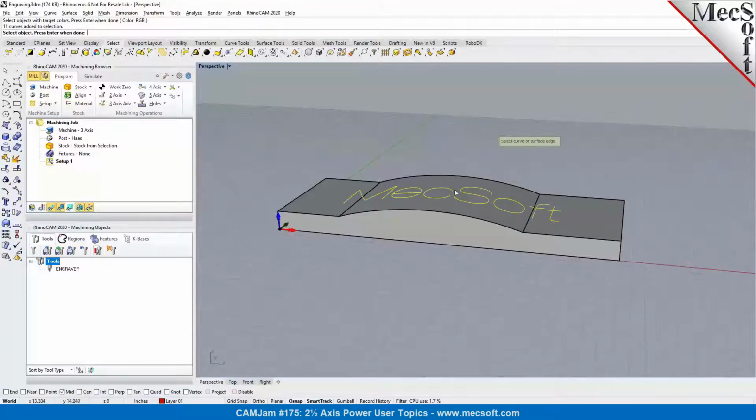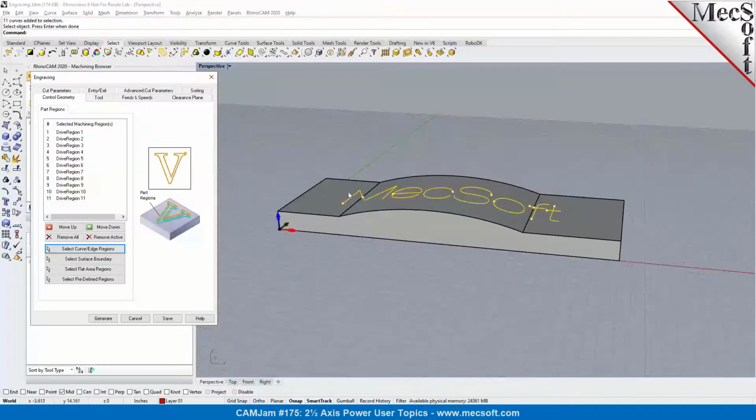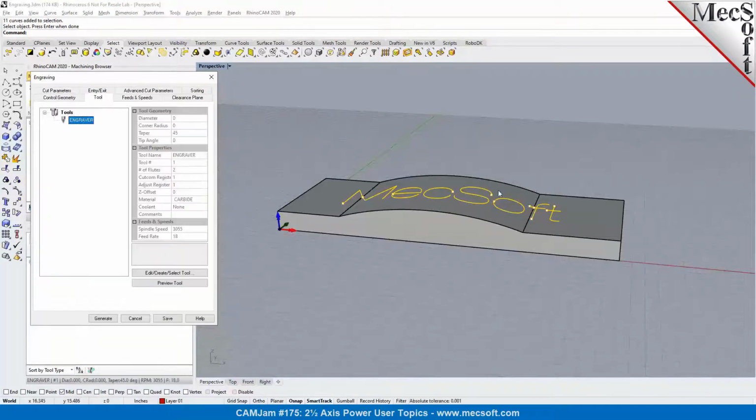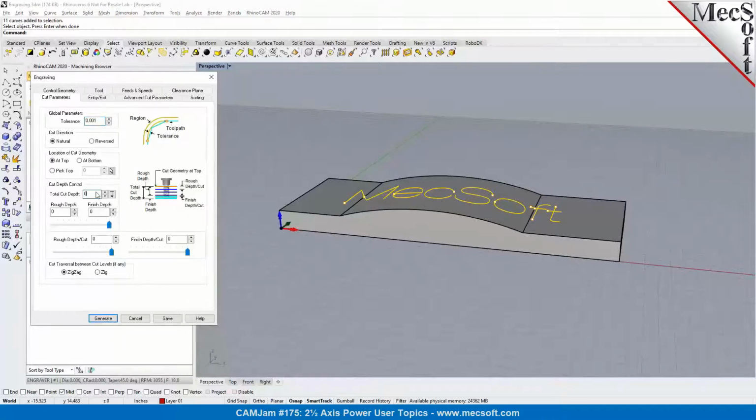Now you may notice that we have a single stroke font. I'm going to show you how we can avail that single stroke font. We've developed a single line font, and you can download and install it onto your computer, and you can define text using single stroke fonts, and use the project command in Rhino to project those text onto the surface. And now when I specify a total cut depth in here, so I'm going to do a 50 thousandths depth, similar to what we did before.